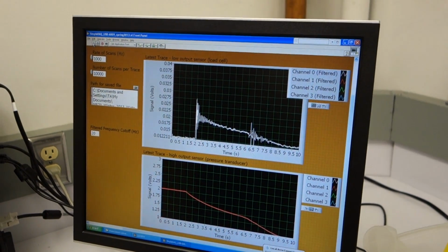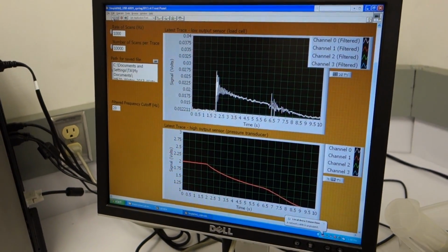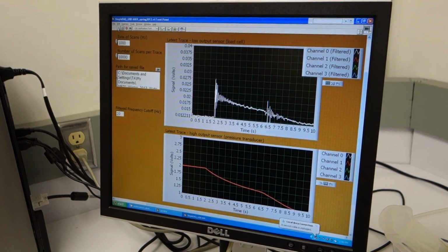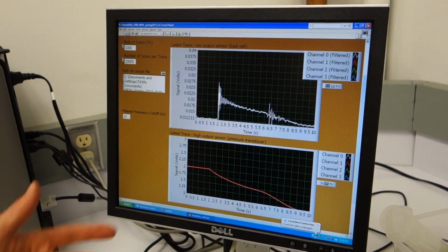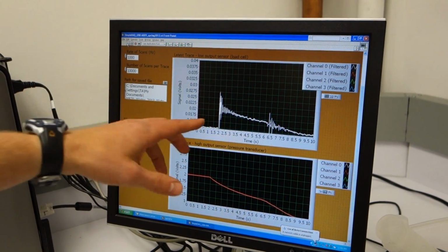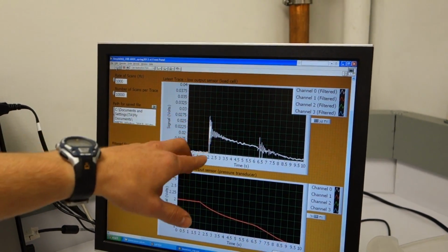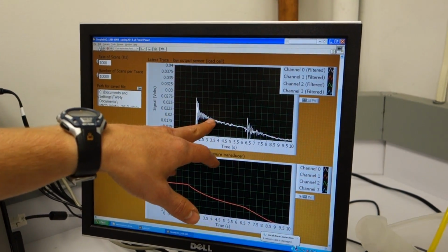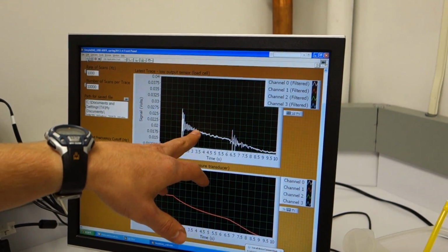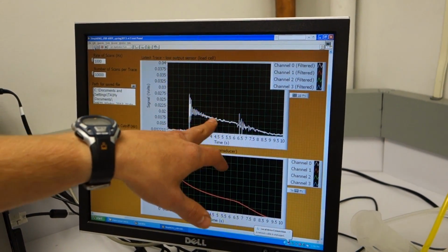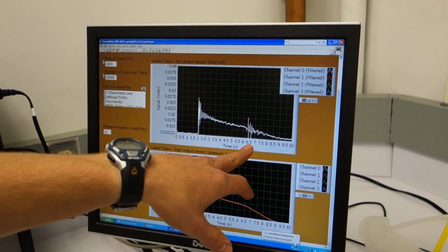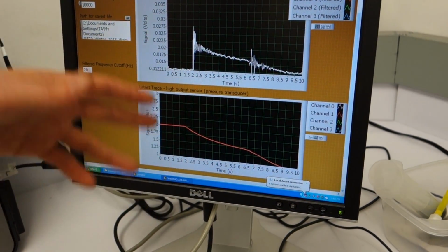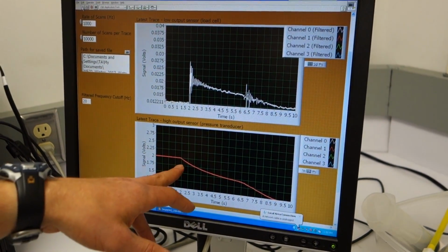And the reason for that is just because we are impacting the load cell, and there's going to be some bouncing back and forth of the whole device. So we're visualizing the damping characteristics of the whole setup. The oscillations are getting damped out until we reach some sort of a constant force applied to the load cell, or at least a steadily declining force. And the same thing occurs at 6.5 seconds. We'll notice on the pressure plot it's smooth just because pressure is not as dynamically measured.